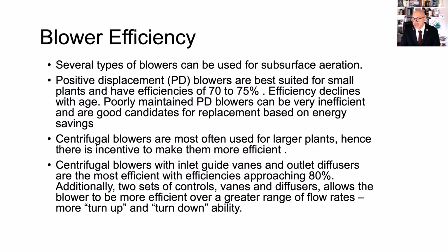And the discharge vanes on the other side, or the guide vanes, what happens is they change the pitch at which the air that goes through the centrifugal volute exits. So they could be along the air streamline, or cut it a little bit, or be across. And so what happens is you can use those instead of using just a regular butterfly valve to change the flow and regulate the flow at the discharge point, not just downstream, by creating a pressure drop. So that way you can have a turn up and turn down ability. You don't run them only at fixed speed.